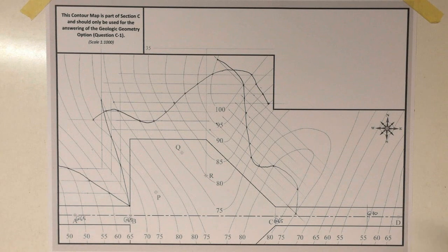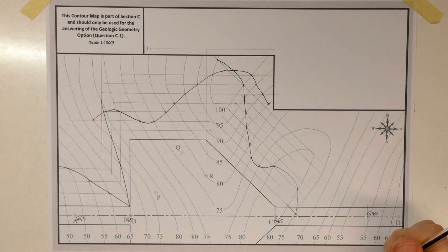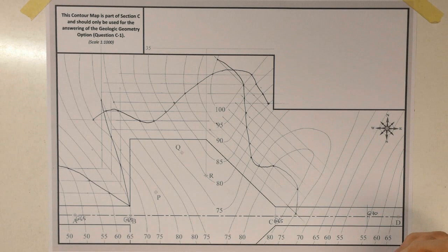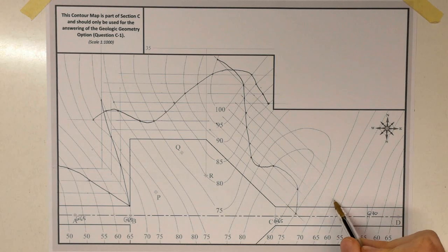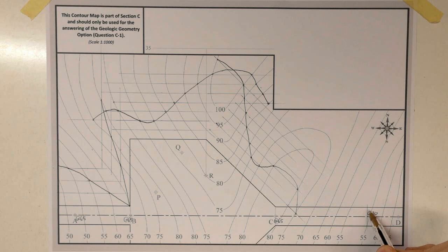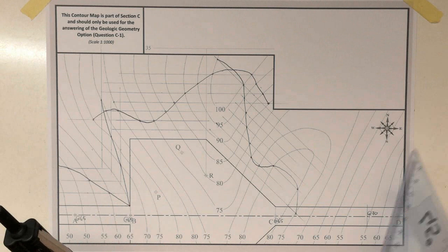That's perfect. Right, and looking, we're rising, so we're going to have to create a cut cone. Okay, we're going between 65 and 70, and underneath, the road is underneath here, so 65, 70. So I'm going to have to cut for a portion of this. Okay, and then I'm going to have to fill. So cut, my cone there is going to be 7.5.